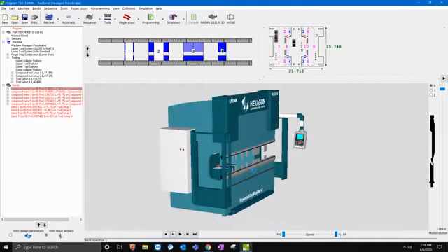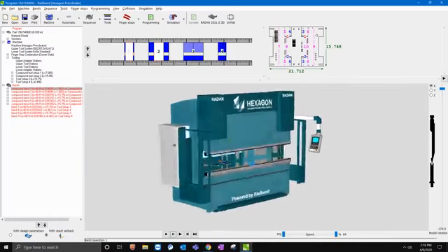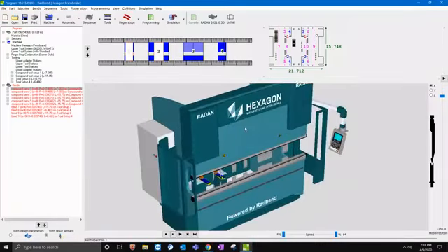So if I zoom back out and I rotate this around, right, I can hit there and rotate. Now, you can actually save different views, right? You may want to save up to 5 different views of how you want to see that. So you can press the F1, F2, F3, F4, F5 button, and it'll change the different views, maybe a side view, a front view, isometric view. So you can change those different views as well, right?